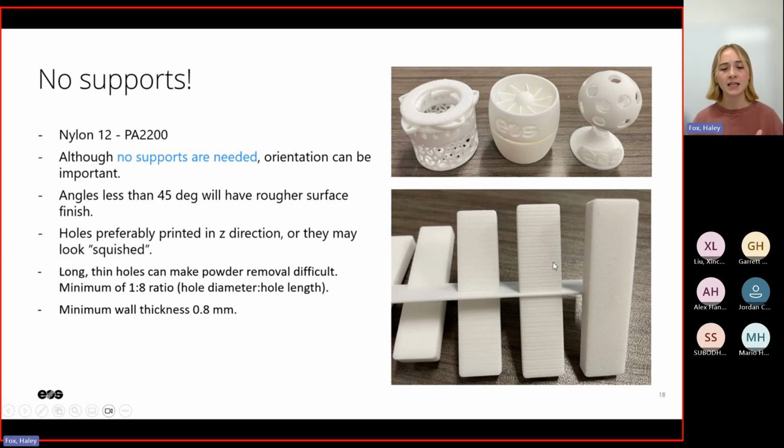The stepping effect is at pretty low angles, maybe 10 to 30 degrees off the XY plane. You can see on the bottom surface and on the top surface some pretty distinct layer lines. We're also printing at larger layers in polymers compared to metals, and so this is another reason why that stepping or layer line effect is so much stronger.